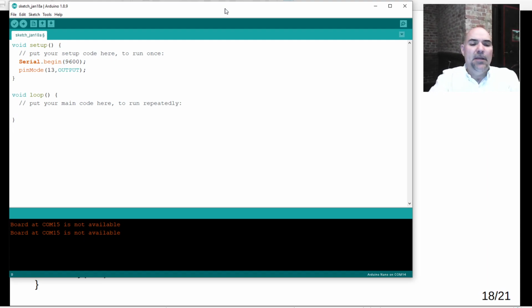All right, and now in my loop function, I'm going to do that digital write, pin 13. We'll set it high. And then we'll do a delay of 500.